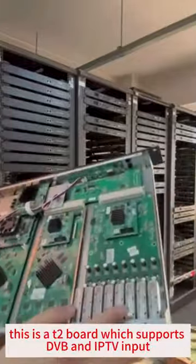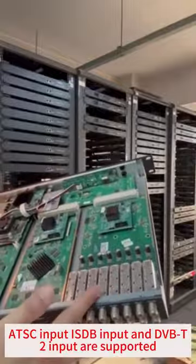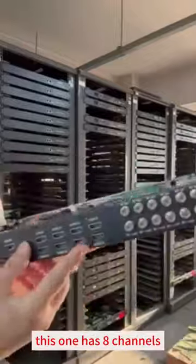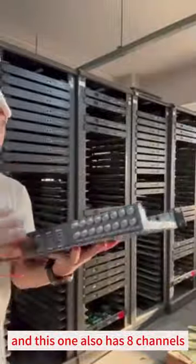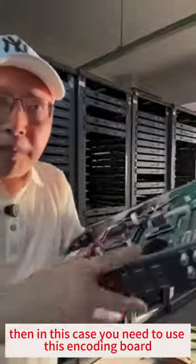This is a T2 board, which supports DVB-S input, ATSC input, ISDB input, and T2 input. All are supported. It's a single board. This other one is an encoding board. This one has 8 channels, and this one also has 8 channels. If your signal source is HDMI, then in this case, you need to use this encoding board.